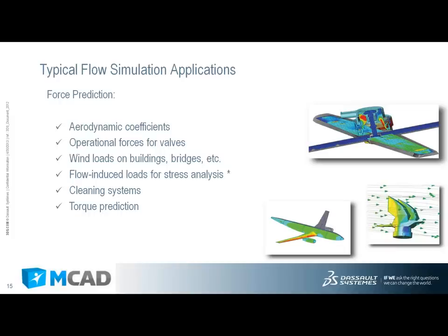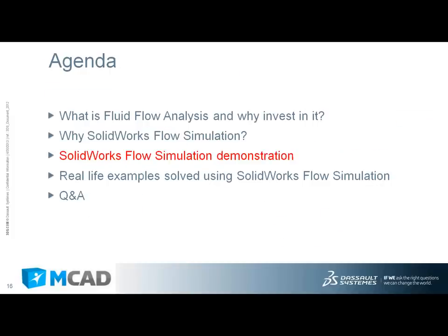I forgot to mention when we were talking about heat transfer effects, we can also bring that information over as well. So for instance, if we had a thermal stress problem that we wanted to solve, we'd be able to bring the temperature distribution from our flow project as well as convection coefficients over into SolidWorks Simulation. So, quite a good interaction. Another benefit to having the program working directly within SolidWorks, it interacts both with the 3D CAD geometry and the finite element analysis package.